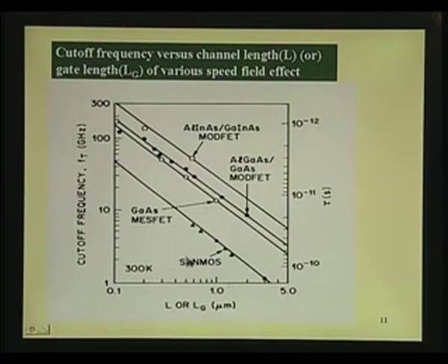Now, if I have an alternate material, we will see how later on, you can see in this graph, all these open circles, the cutoff frequencies are higher than silicon. For example, you can see what you get with 1 micron with this gallium arsenide based field effect transistor, that is something like 10 to 15 gigahertz range, I am sorry, gigahertz, megahertz nobody talks of these days.